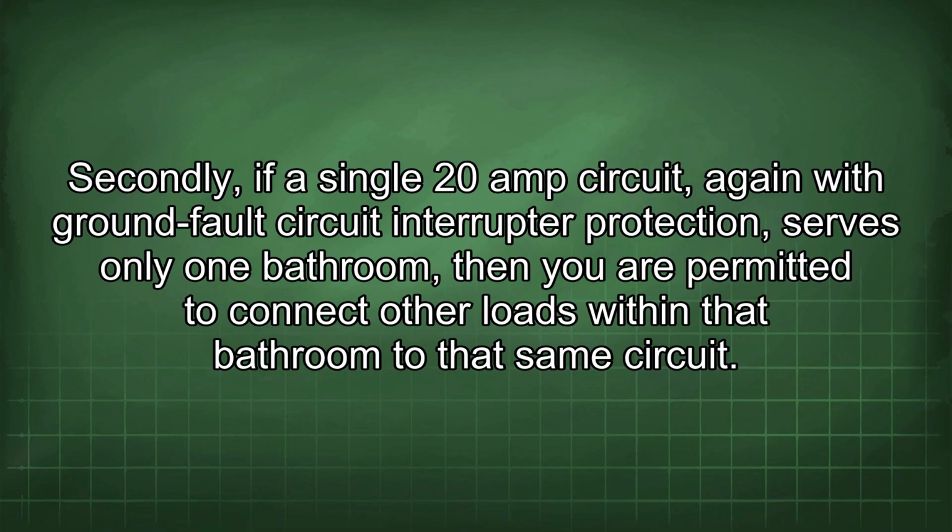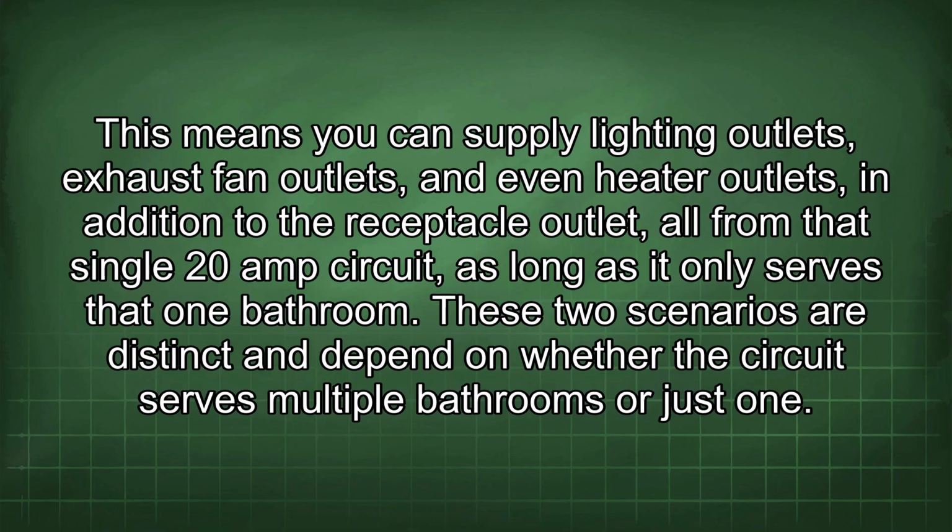Secondly, if a single 20 amp circuit, again with ground fault circuit interrupter protection, serves only one bathroom, then you are permitted to connect other loads within that bathroom to that same circuit. This means you can supply lighting outlets, exhaust fan outlets, and even heater outlets, in addition to the receptacle outlet, all from that single 20 amp circuit, as long as it only serves that one bathroom. These two scenarios are distinct and depend on whether the circuit serves multiple bathrooms or just one.